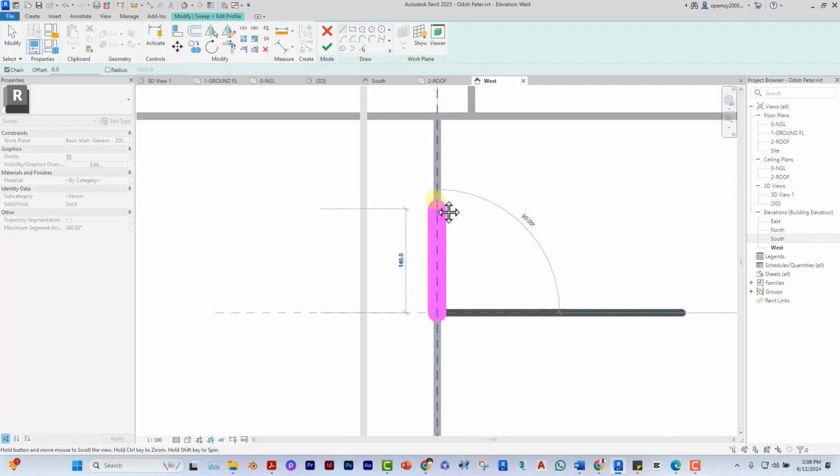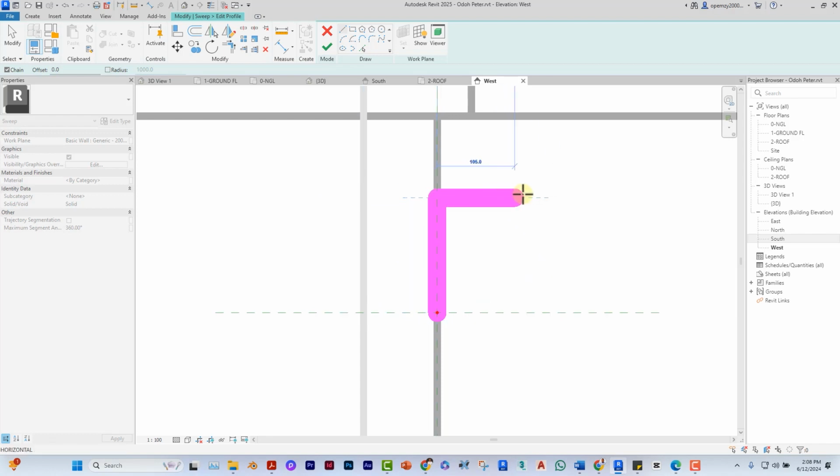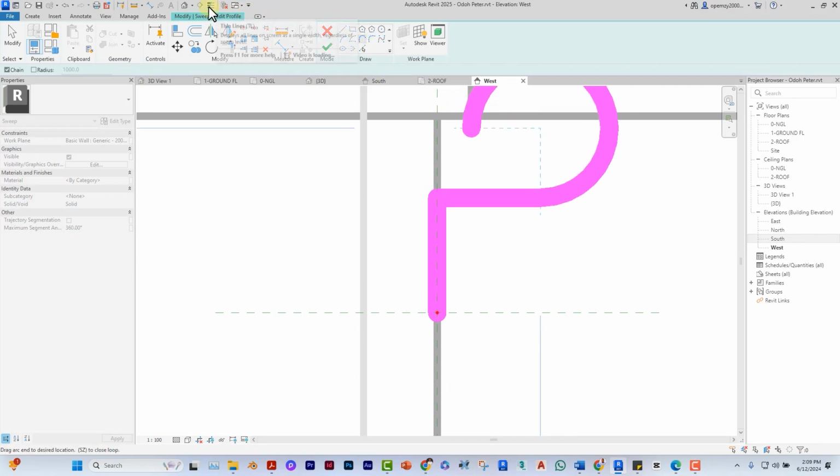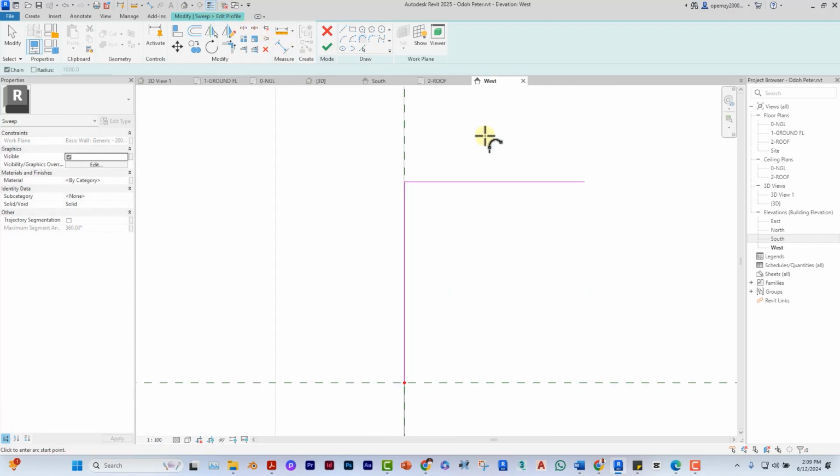I'm going to say this profile is like 155 mm by, let's say, 140. And I can do a tangent here. Let me click this line here, T lines, to make the lines thin. I hope you can still see what I'm working on. I use the tangent to do the first curve, maybe the second curve.